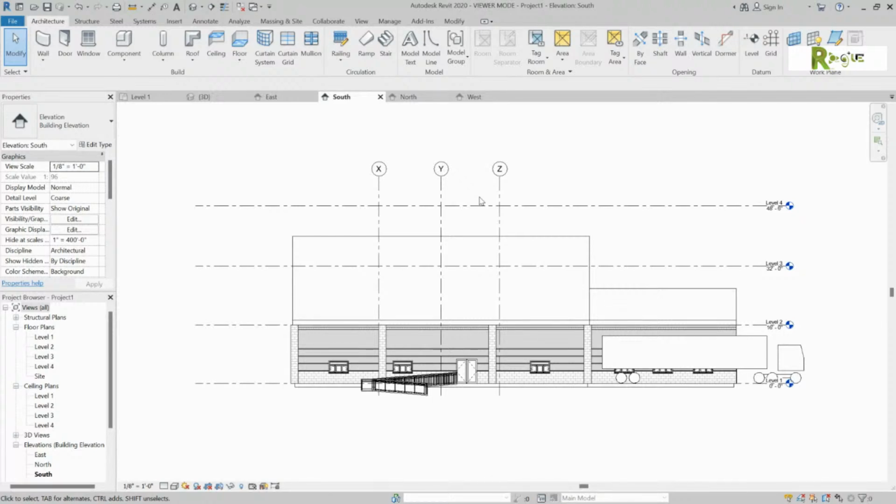Gotcha. Okay. Now, typically for larger buildings, for steel structured buildings, the first thing you're going to do is put in those grid lines. And you're going to say, I've got a 30-foot bay or a 20-foot bay or whatever it is. That's usually some of the first work you do on an industrial building. Typically, a residential house, you're never even going to worry too much about the grids because there are no columns.